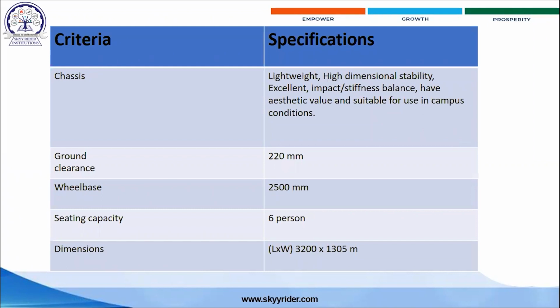If we are using an electric vehicle with a low cost budget, then your battery power will be low. If your battery power is low and you make the chassis heavy, then what will happen? Your sitting capacity and loading capacity, meaning your luggage and seating capacity, will decrease.